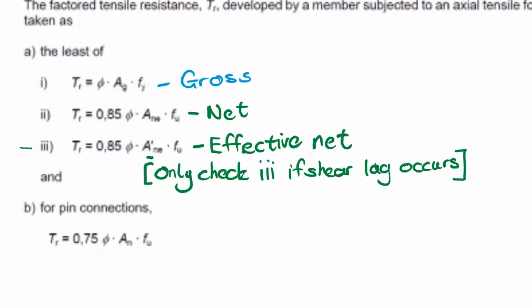So lastly then, for pinned connection, this is for a single bolt in flat plate kind of idea. It's a pure pin, single bolt dowel type connection. Those are not common, but there are guidelines for that if you have a single point that you connect. Normally you have 2 or more bolts that you'll use in terms of your connection design.